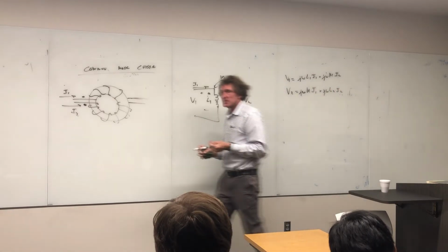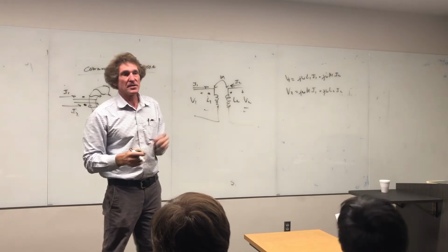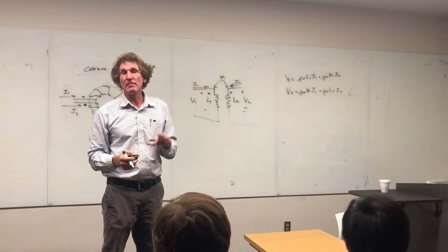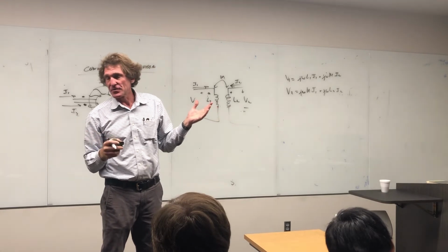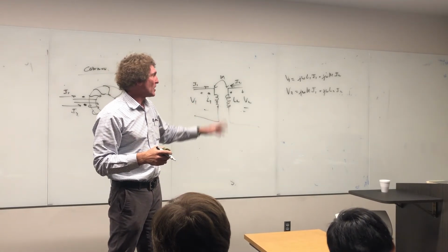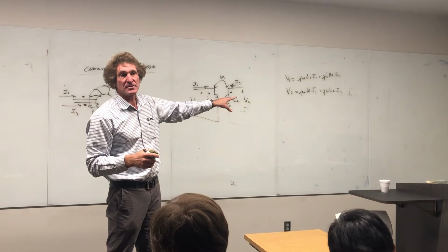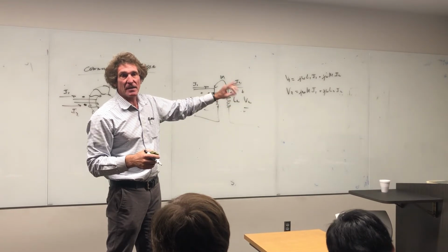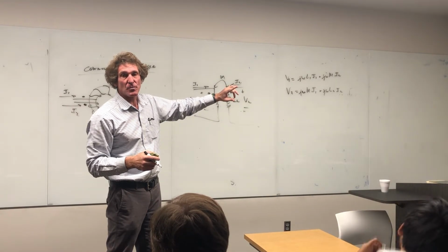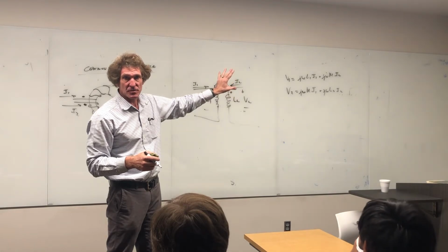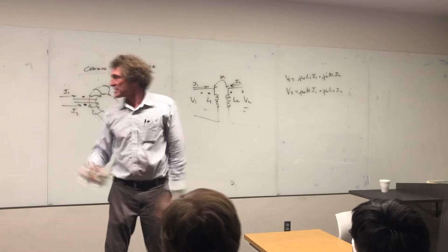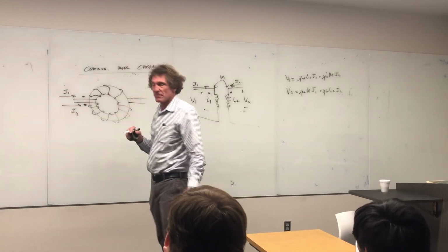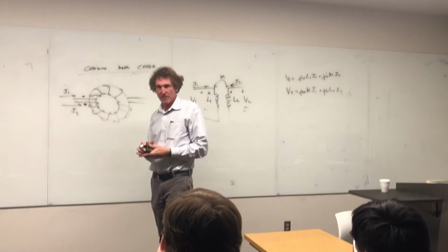Now that's the relationship between the voltage and currents in the primary and secondary for a magnetically coupled circuit. I could make that into a transformer if I took L1 and L2, multiplied them by themselves, and said that was equal to M squared. That would be a transformer where the coupling was good, and then these would break down to simple transformer equations. But because this isn't highly coupled, it's not going to be super highly coupled.